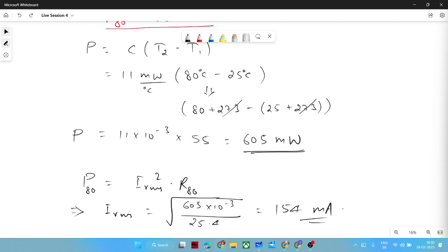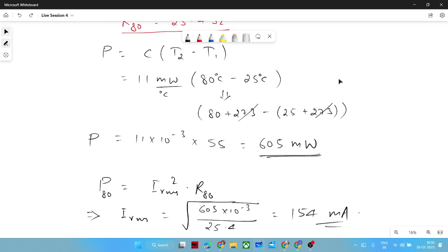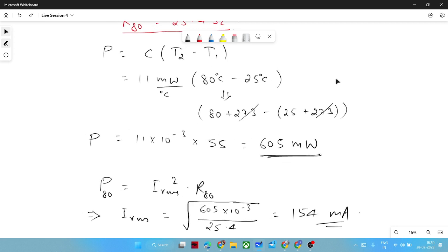Do we have an application of thermistors as inrush current limiting really in practical use, or is it just a theoretical one? No, it is practical, right? Thermistor is a practical thing. You can use it wherever the desirable application. If you need to have rugged and cost effective, then you can go ahead with thermistor. Otherwise, you can use MOSFET kind of things. Or if you are not worried about power density of your converter, you can go ahead with transformers.